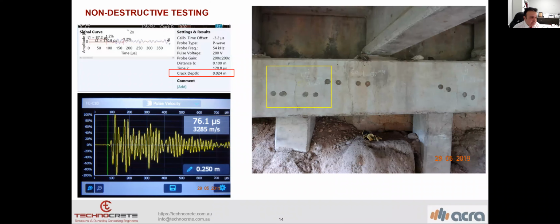Yeah, so it increases the investigation. Exactly, yes. All right, two questions, hopefully short ones, about NDT. What is the best and recommended NDT for crack depth estimation? Ultrasonic pulse. This is the current slide which I'm going to present, regarding the crack depth. And the other one was about how you measure moisture content with NDT methods. Oh yes, we have to do the moisture content test, especially when we want to use CFRP wrapping as strengthening of the structure.